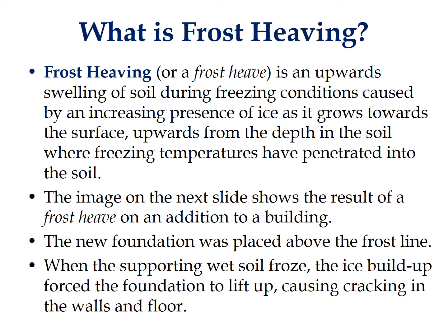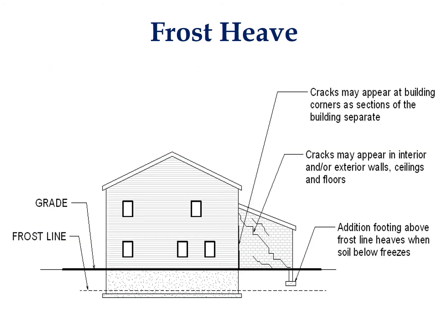When the supporting wet soil froze, the ice buildup forced the foundation to lift up, causing cracking in the walls and floor. Here you see the damage caused by a frost heave. Cracks appeared on the corners of the building and in the interior and exterior walls and ceilings and floors, all because of a frost heave.